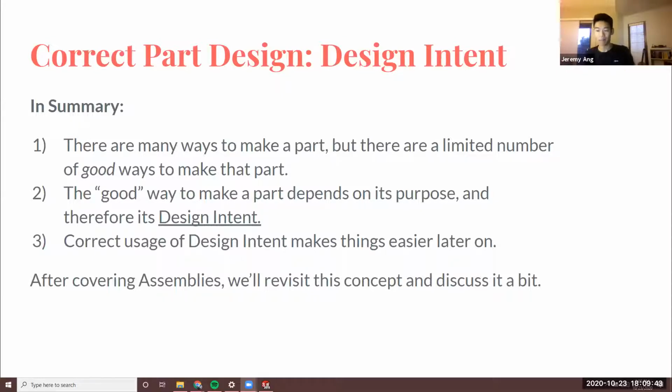So that's an example of bad design intent and good design intent. In the end, it made the same part, but once I had to go in and try to change something to fix it, the badly designed piece got messed up. When I changed it to dimension the holes to the cutout, no matter how long I made the box, no matter where I put that cutout, the holes always stayed in place, and in practice, the circuit board will always properly mount onto the box.